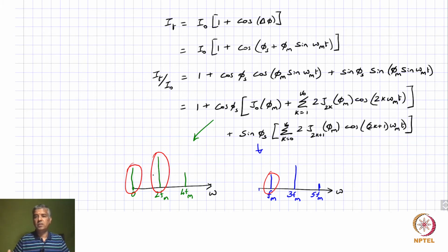Of course, we did start by saying that in a FOG the external perturbations are not as high compared to what you would normally have with a Michelson or a Mach-Zehnder interferometer. To start with, you have relatively no noise, but as you increase the rotation rate, some of those noise components start showing up, and in that case, this scheme actually helps to suppress all the external perturbations.